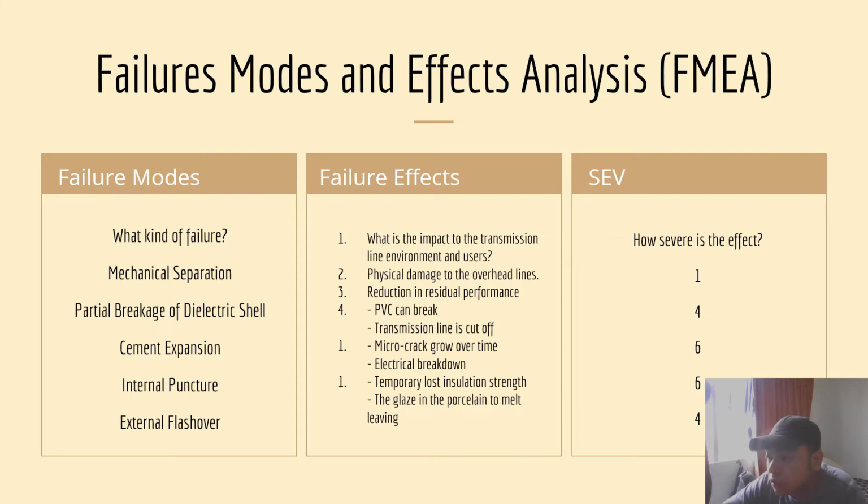The internal puncture is a micro crack that grows over time. That's the failure effect, and the severity is 6. The external flashover is a temporary loss in insulation strength. The glaze in the porcelain melts and leaves. That's the failure effect, and the severity is 4.